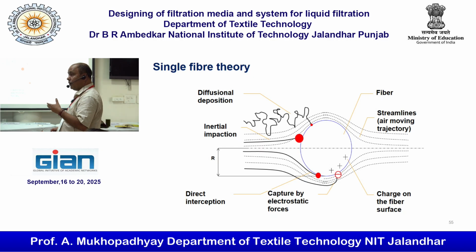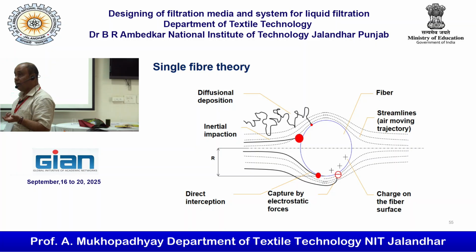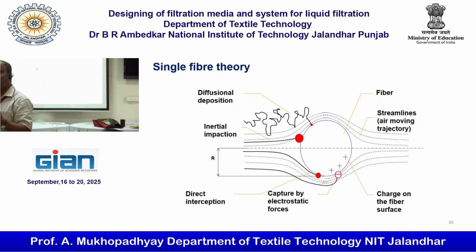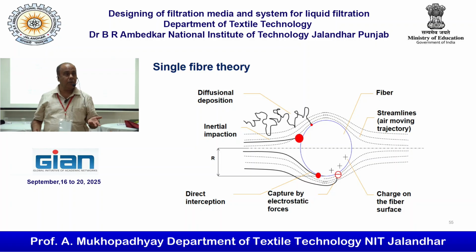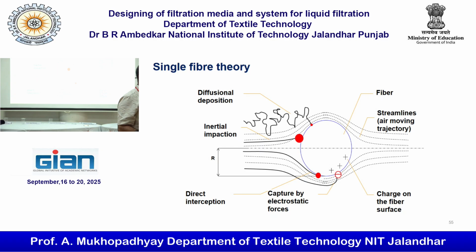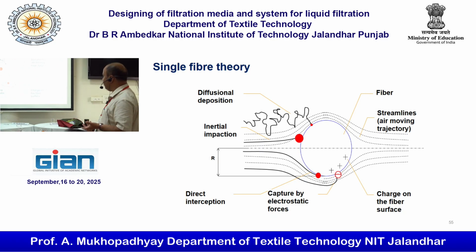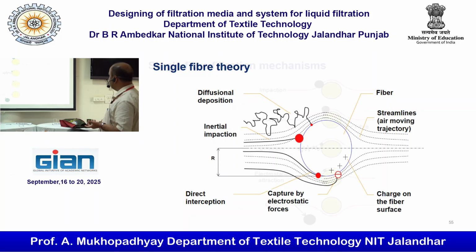In many places people try to develop electrostatic media also, but the problem here is that initially it will function, but after a certain duration it will not function. So that is also a commercial aspect of selling these things. It will not function after a certain period of time. Charge on the fiber surface can also capture the particles. So this is the single fiber theory.